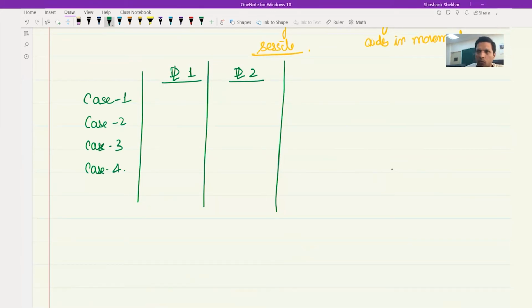So in case one, when I say dislocation one, it means the step on the dislocation one. We have seen it is a jog and it is of edge character. For dislocation 2, we saw that it is not applicable because the step was formed along the line direction, which doesn't mean anything. For case 2, the step was a kink and it had screw character. In fact, both of them had screw character and they were kinks.